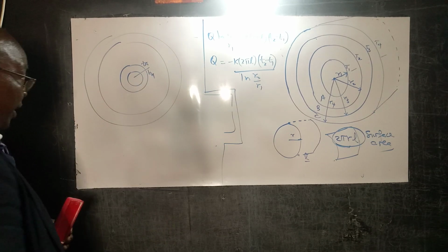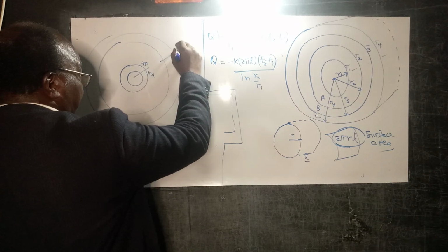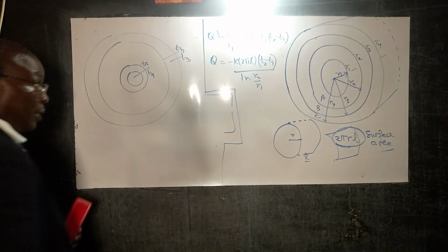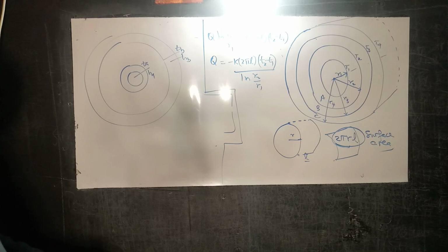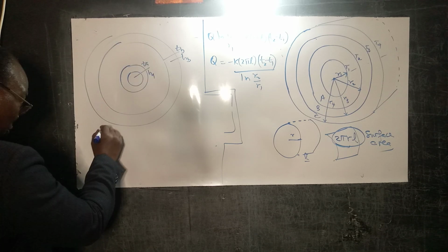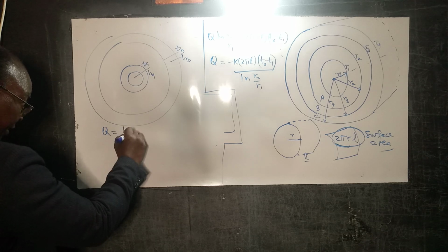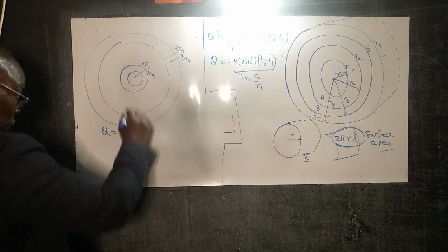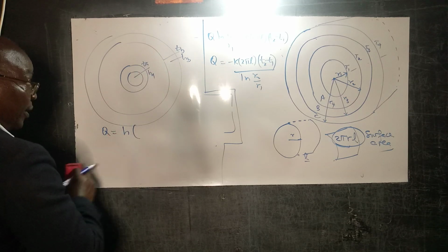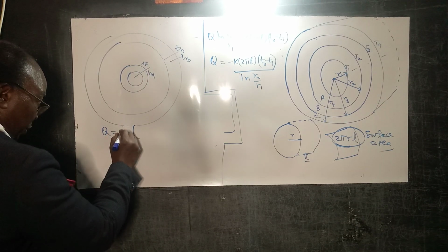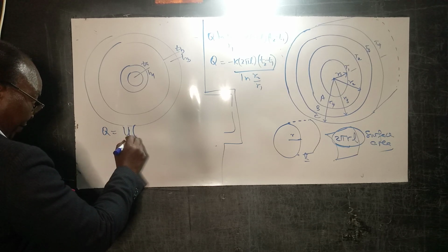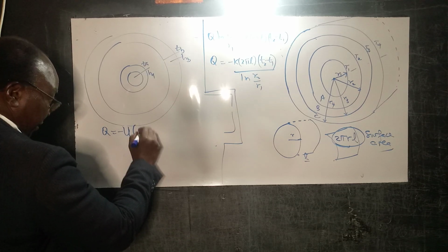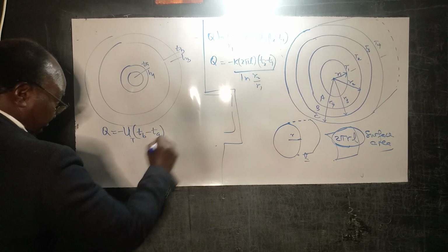The coefficient is HA. The outside pipe is TB. Coefficient is HB. So for this particular system, in general, Q here will be simply that overall heat transfer coefficient into, let's be consistent, let's call it U, the overall heat transfer coefficient, times T, minus, that is TB minus TA.